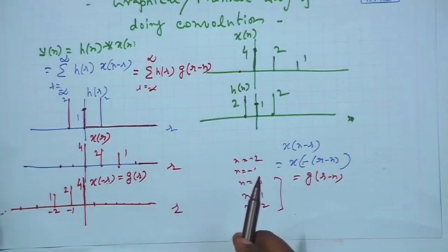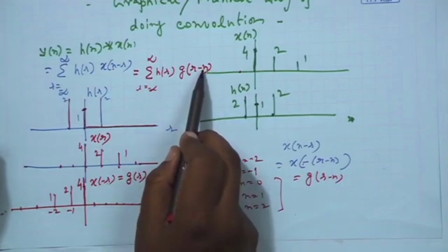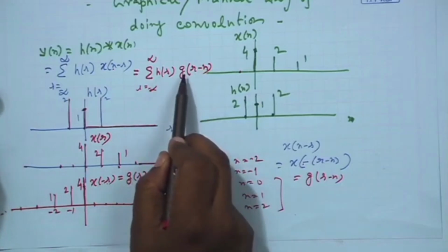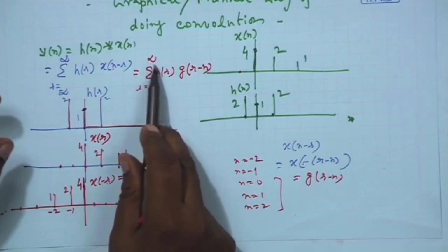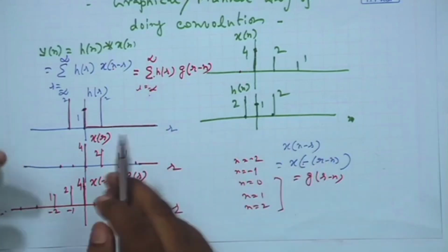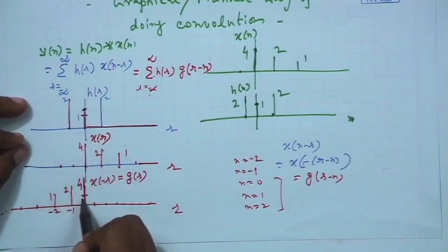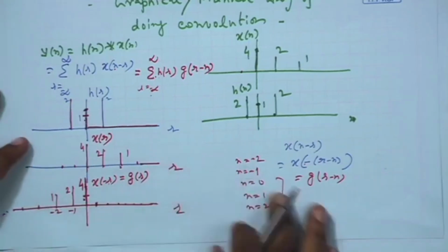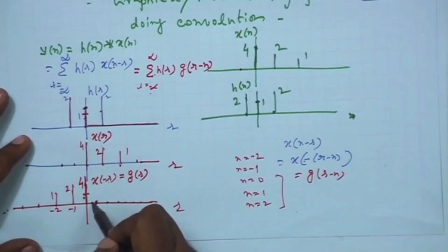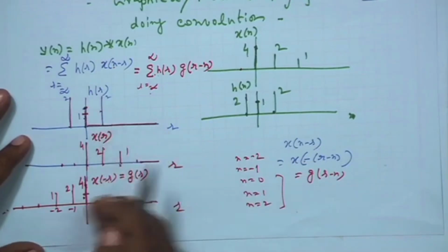So, now we have to find out this convolution at, to start with, n equal to 0. So, h[r] g[r] we have to multiply. What is g[r]? This. So, h[r] into g[r] for every r equal to 0, r equal to 1, r equal to 2, r equal to minus 1, like that I have to find out, multiply and add. So, h[0], this guy g[0], we multiply, we get 1 into 4. Then I have 0 here, non-zero, so product is 0. This side is 0. So, right hand side nothing.